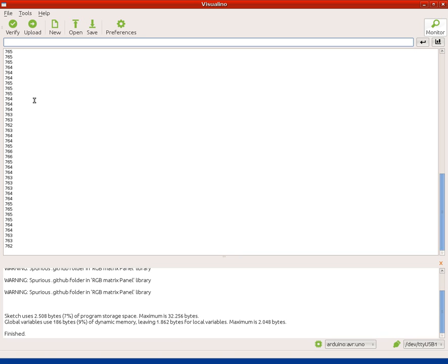As I have my LDR connected to 5 volts and the fixed resistor in the voltage divider connected to ground, maximum voltage could be at most 5 volts and minimum 0, so numbers will be in between.